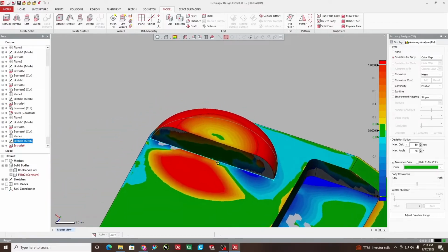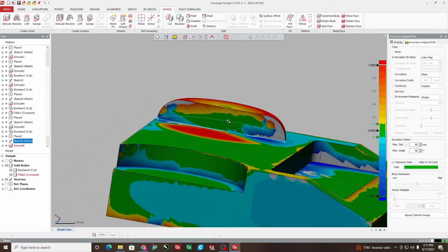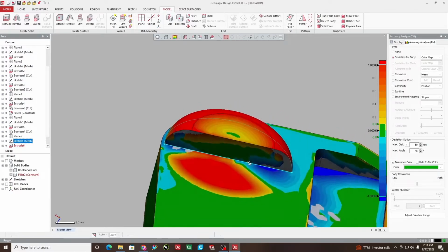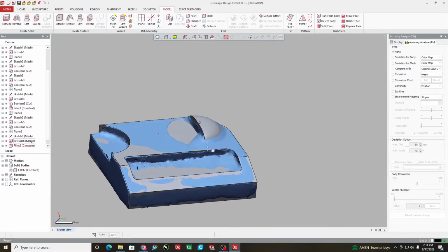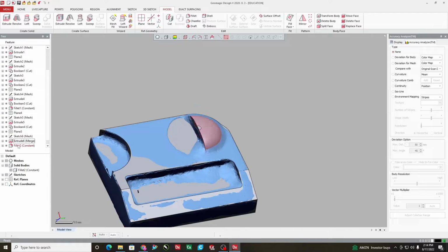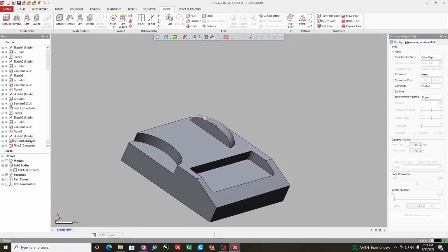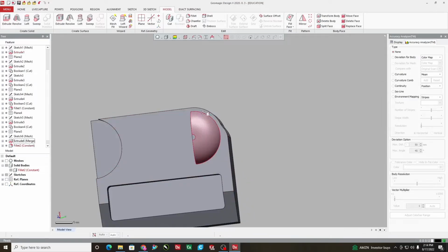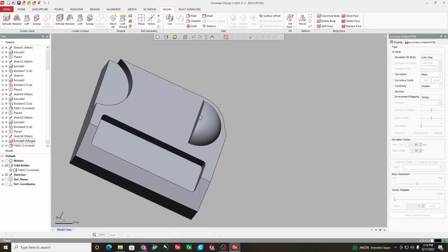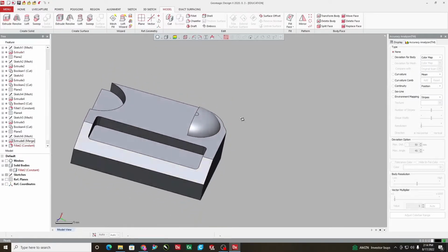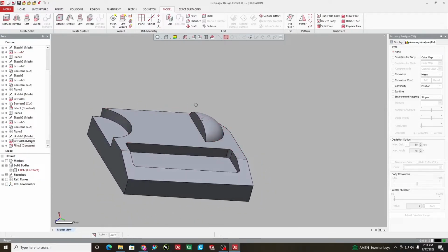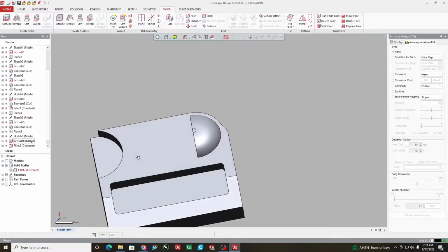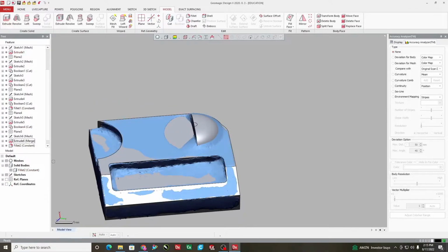So the camera lens that we used had 25 mm focal length. So that is why it has given the great or the close data that we have got. So we have created the dome while keeping on matching the curvature to the mesh body and getting the green part as close as possible. There are certain small points that we need to take care of when we try to scan, like the temperature of the room must not be more than 32 degrees, and the field of view is within 760 mm. So these points we need to take care of.